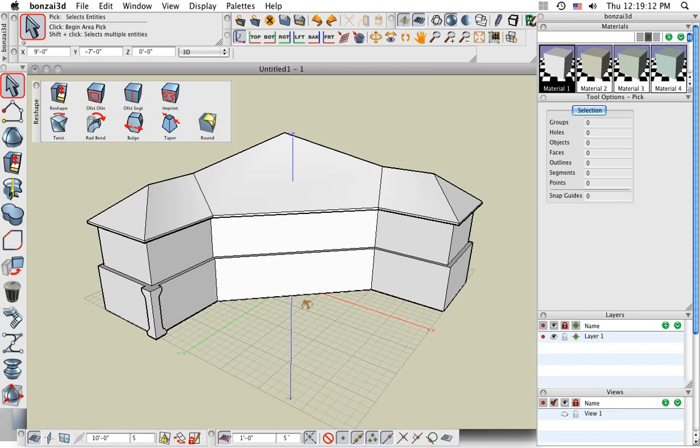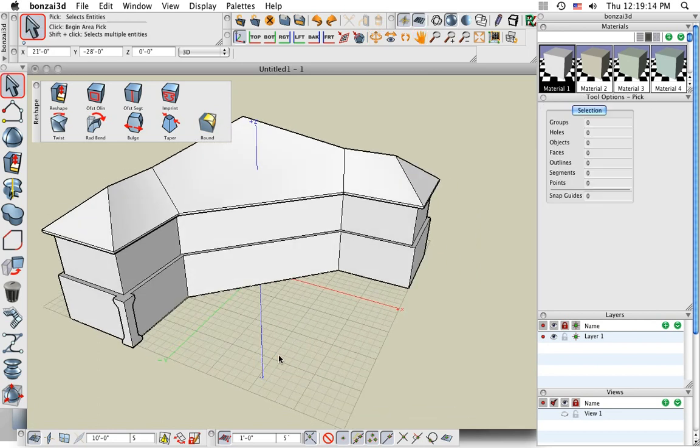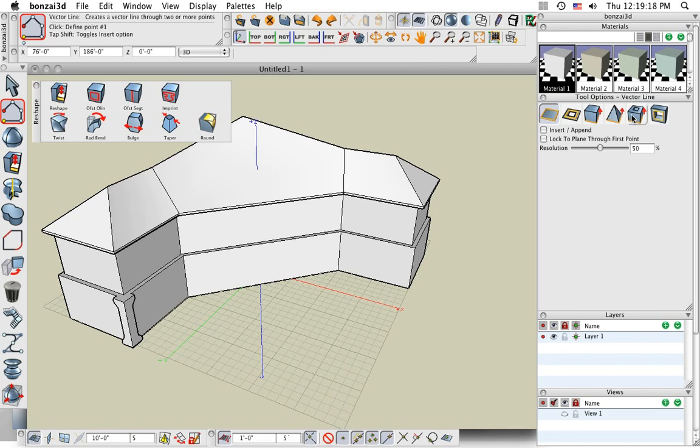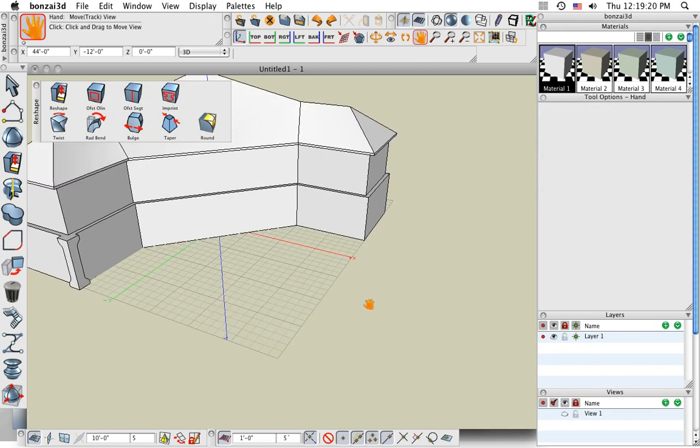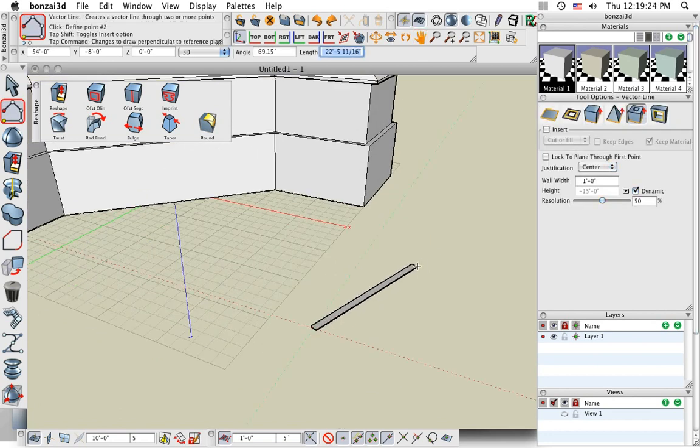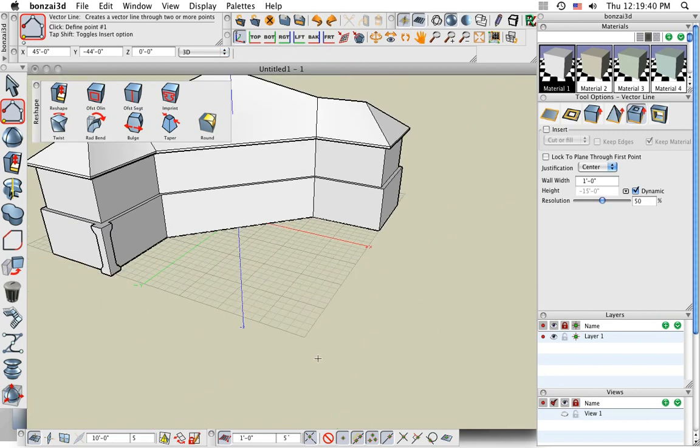because guides are a very important thing when you're modeling to help really speed up that modeling process. There's a few different ways that those guides help out. One would be if I'm drawing a wall. For example, a vector line is a 3D wall here. Notice that when I click, I do get these automatic guides that show up. So I can click on the red guide, x-axis, the y-axis, that is tangent, that is perpendicular. And no matter what I'm drawing, arcs, curves, whatever, I get these guides that help me make sure that things are lined up exactly how I want them to be.